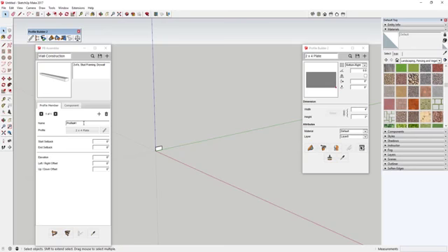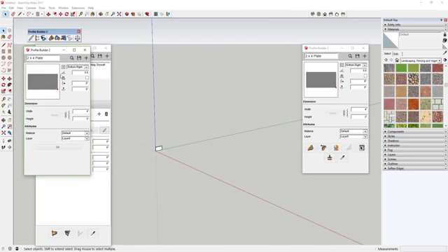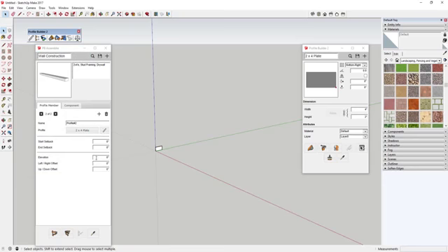What we're going to do now is, you've got one 2x4 plate that it brings in at an elevation of 0, so we want to add another one. Just click this plus for add profile member, come in here and select the same thing. Select 2x4 plate, hit OK. For this one, we want to edit this box that says elevation. In this case, we want this to be probably 8 foot 4 inches high. So you can type in 8 foot 4 inches, and you can see that it gives you a preview of your object. And by the way, you can click on this to refresh it.